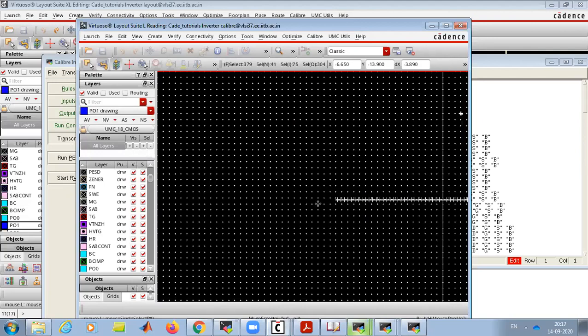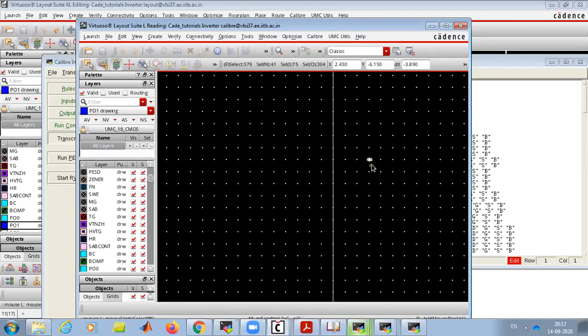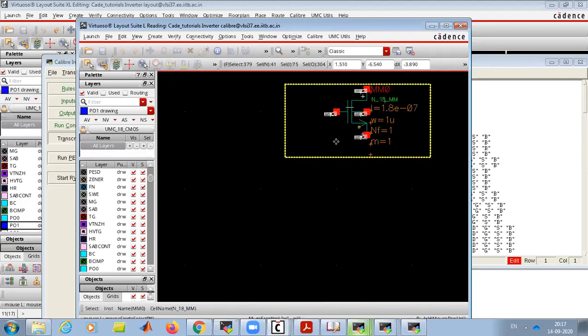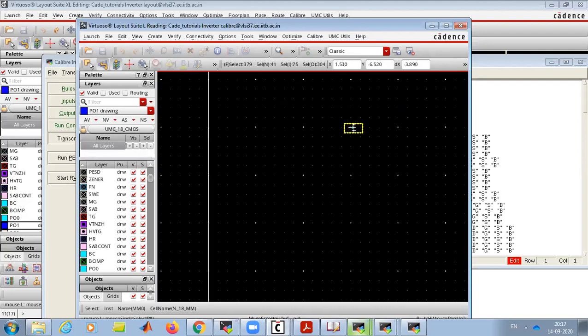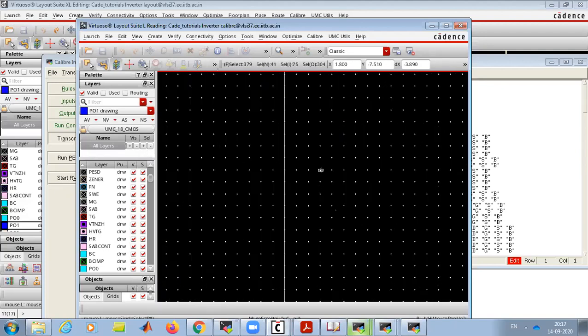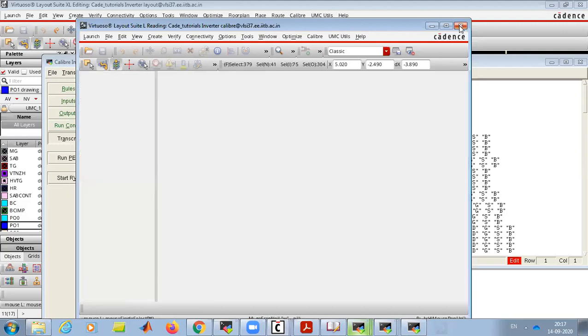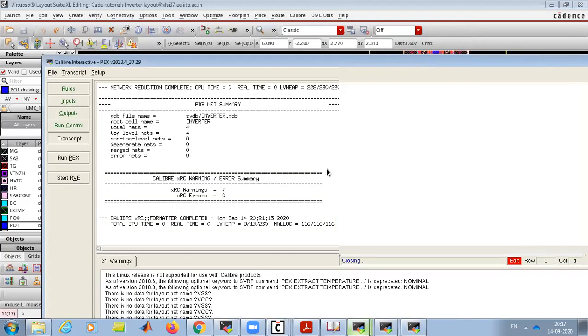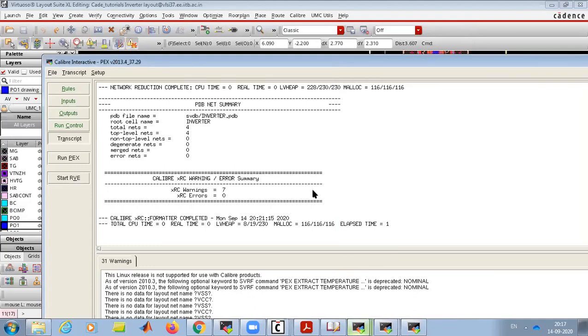Now, when we did our schematic simulation, we used only this transistor. Now with these parasitics, how our circuit will perform and how we'll do the simulation, in just 5 minutes we'll see. So the advantage of parasitic extraction is that in some very high speed design circuits, we need to restrict our parasitics also, because it will reduce the speed or bandwidth of the system.